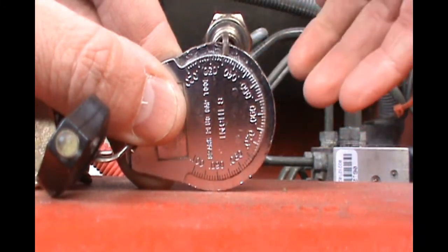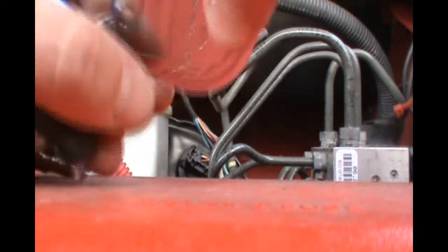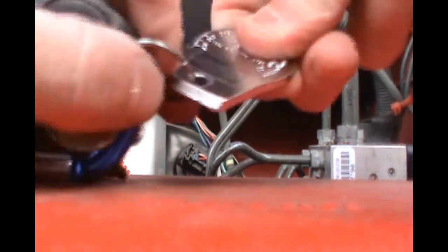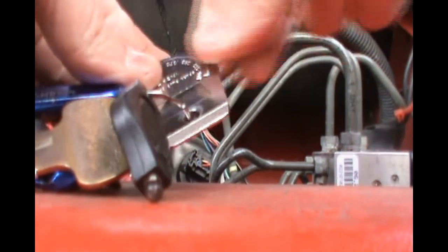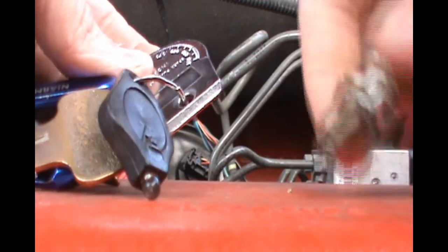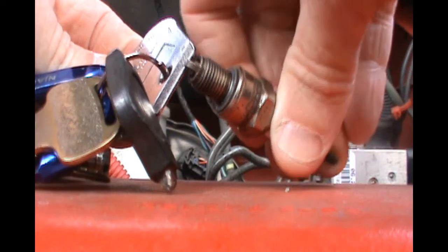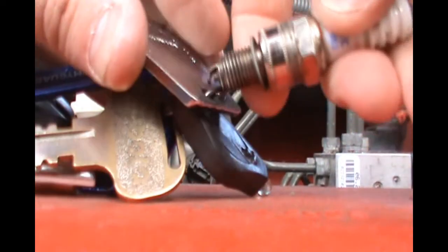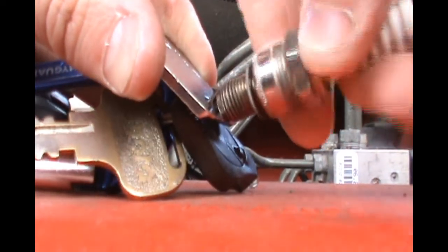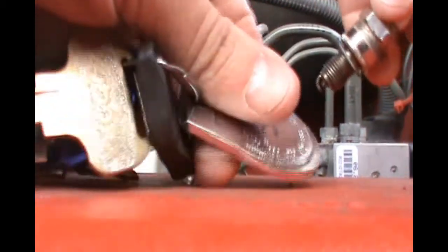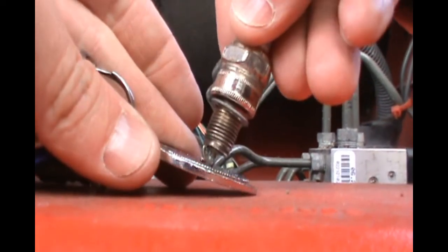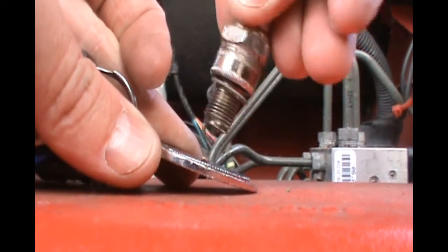Now, if it's not at the correct gap, a lot of them leave a little room or they have a little hook on the bottom of the tool. You can see the hook here. I can put my spark plug on there and I can bend it a little bit to make the gap wider. Likewise, they have a round hole on them that you can hook the spark plug into and make it bigger. And if you want to make it smaller, you very gently apply pressure, or some people tap them down.